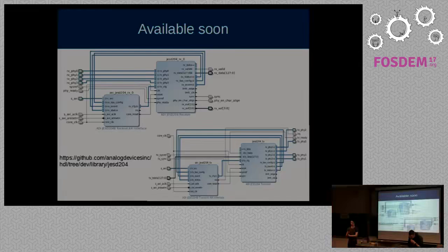Yes, you can, but then you don't get the deterministic latency, because your recovered clock will have a random phase. You recover the high rate clock, and then you create a down-divided clock for the parallel section of your processing, and the parallel clock will have random phase relative to your transmit parallel clock. It won't be random itself, it will jitter. No, we can talk about this later.